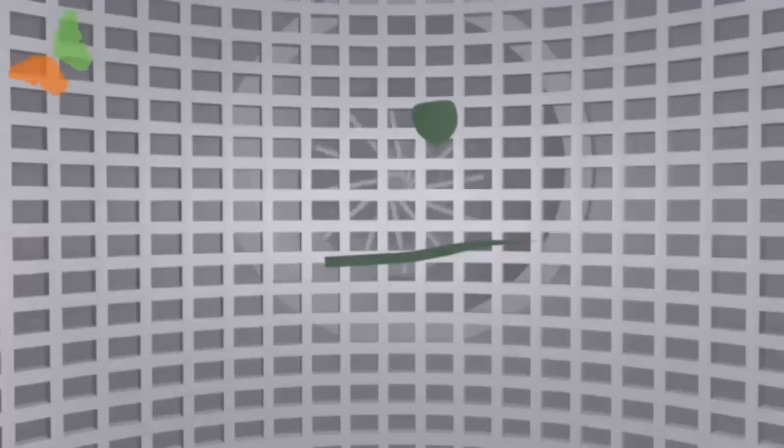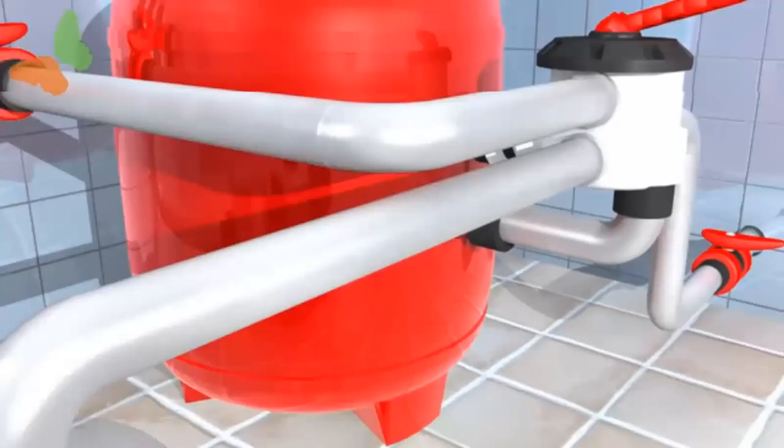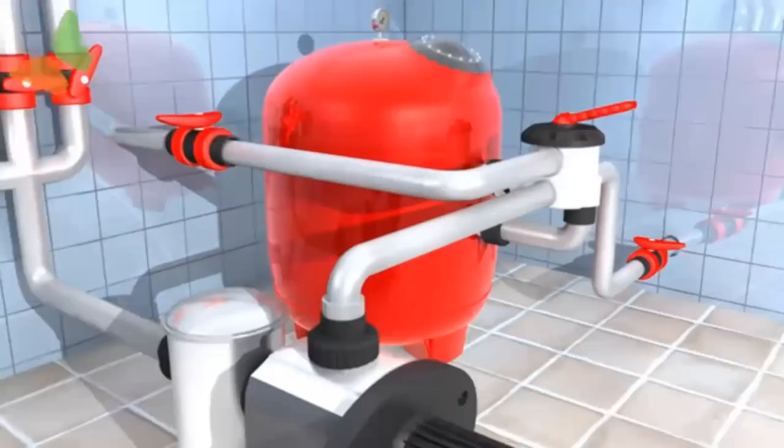From the drain and the skimmer, the water travels through the piping, where it reaches a second basket, placed just before the pump propeller which moves the water. This is the pre-filter of the pump. In this second basket, smaller objects such as hair, small leaves and grass that have passed through the first basket are retained. The propeller of the pump moves the water towards the main filter, and it is this that generates the pressure in the whole system.